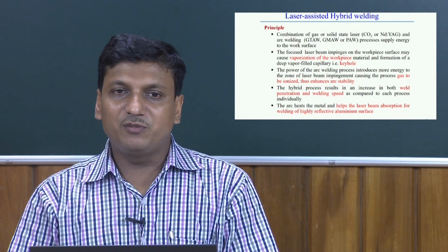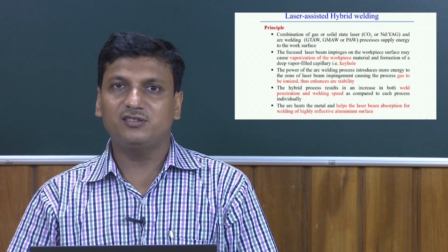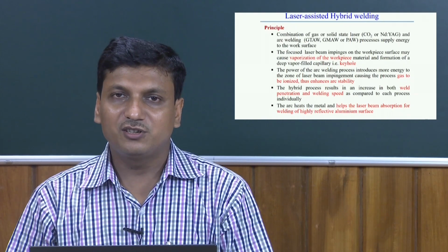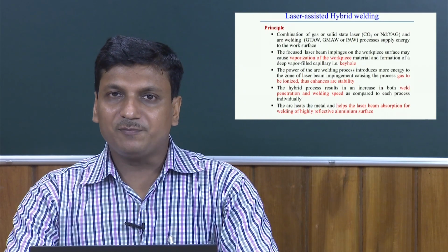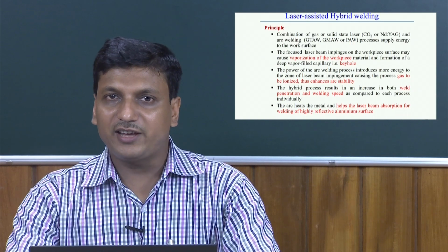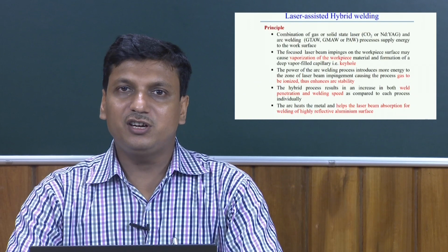Another specific principle it follows: in the hybrid welding process there is an increment of the weld penetration. Basically, we can achieve a high depth of penetration using this hybrid welding process, and at the same time, a high welding speed can also be used in this case as compared to the individual processes.